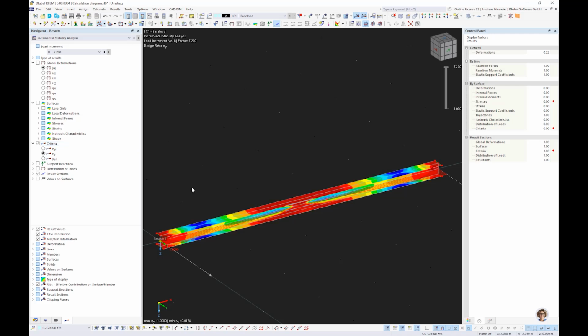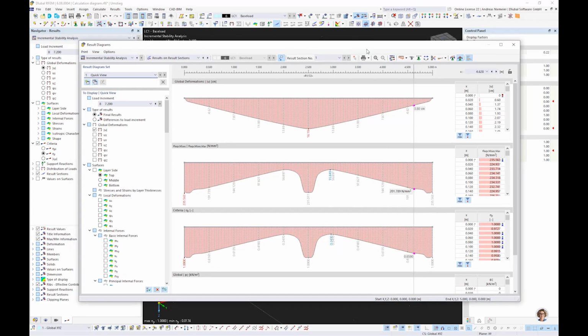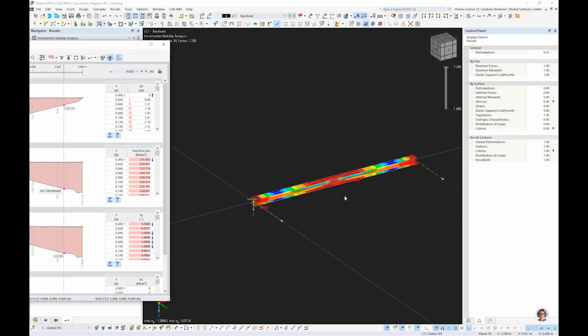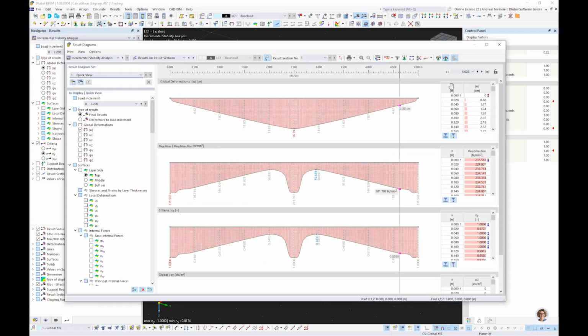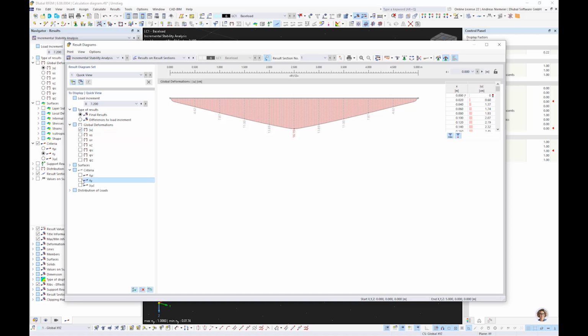But what I like more is to select it and to jump into such a result window. And this is now modal programmed, what is new in comparison to RFEM 5, because you can work at the same time in RFEM itself if you have 2 monitors. And now let's say we want to see deflection, maybe here U, and we want to see here criteria NY,